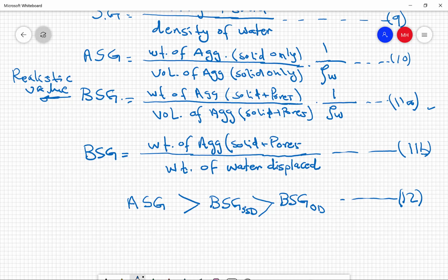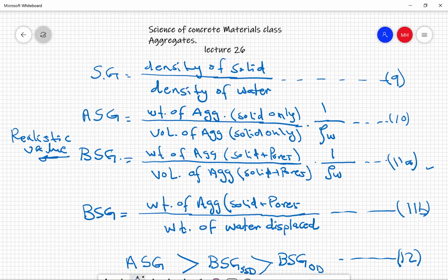The bulk specific gravity, let me go back to that equation. The bulk specific gravity, as I mentioned, of most rocks is in the range of 2.5 to 2.8, if you remember, we mentioned that. So a value well below this range is probably indicative of high porosity. So remember that. But the bulk specific gravity of an aggregate cannot be directly related to its performance in the